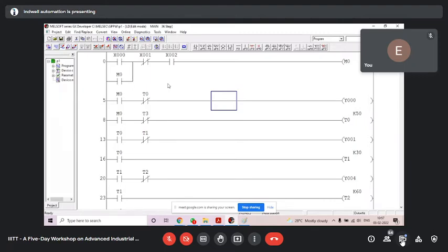All five outputs should be displayed on the HMI screen. I want to operate my machine with the HMI, meaning give the start stop function to the HMI. Third is sensor status should be displayed on the screen. Fourth is all timers and accumulators have to be displayed on the HMI. Correct. And fifth is we have to control the preset value of all timers on the HMI. Very good, very good. So see, how can we do all these things? We will do it practically.